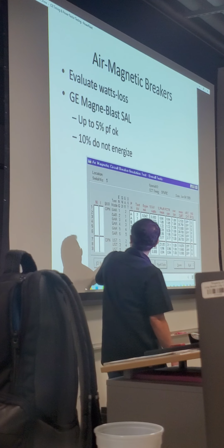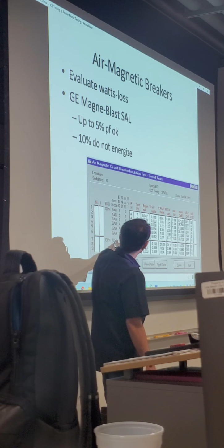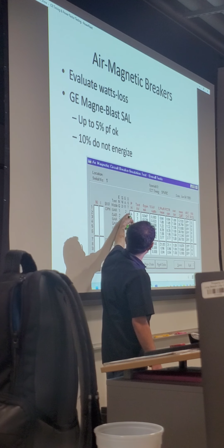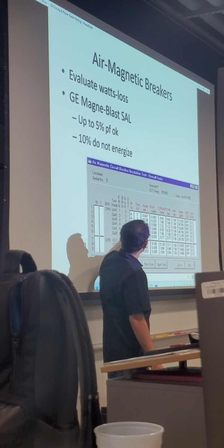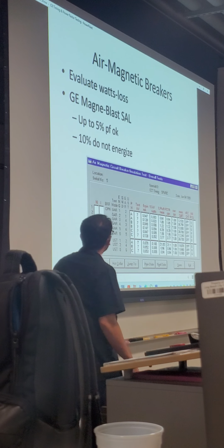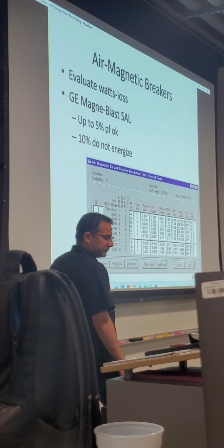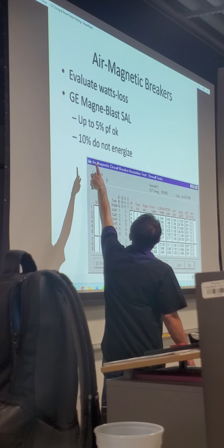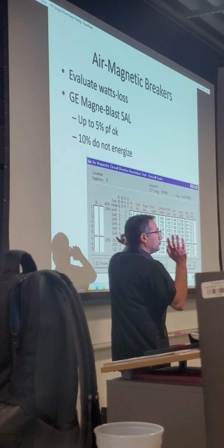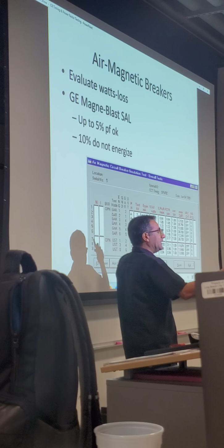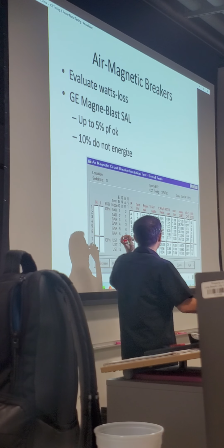These are the UST ungrounded mode, and these are for grounded and guarded modes. You have 2 results A phase, 2 results B phase, and 2 results C phase. The total is gonna be 9 numbers. You hook up the leads, you run the test.